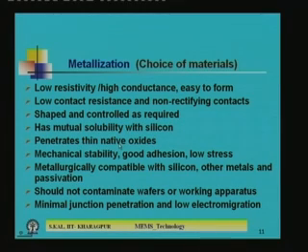So, on top of that you are depositing aluminum. That means aluminum must penetrate through that native thin film of oxide, otherwise if it cannot puncture, you will not get good proper ohmic contact. So, the metal film which you are selecting for metallization must penetrate through that thin layer of oxide.